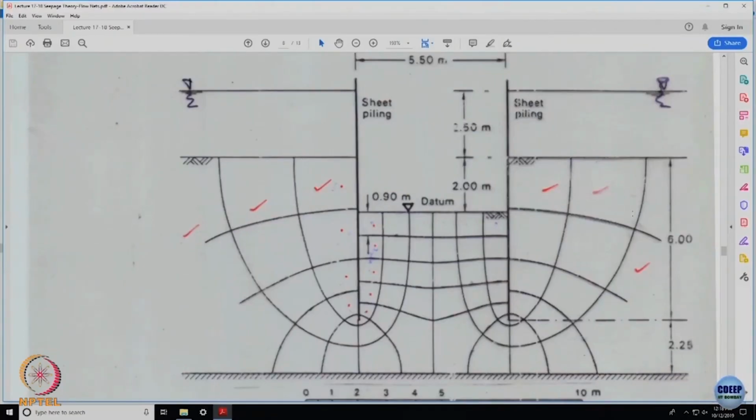This is the flow regime which has got established. From this point to this point, which is atmospheric, I hope you understand the seepage is being caused by this head minus 0. Clear? Agreed? In other words, the head is dropping from this plane to this plane in a number of drops, which I have represented as ND.